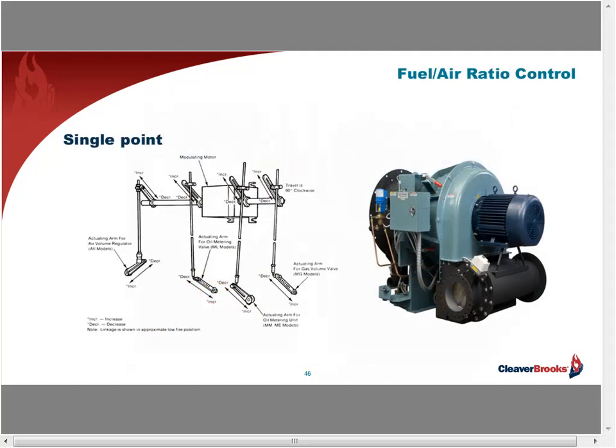Now, moving to the fuel and air delivery on the boiler. If you have a single-point positioning system, as previously alluded to, it is going to wear in time, causing slippage and deflection. This throws off the proper fuel-air mix, wasting energy, as I mentioned earlier as well.